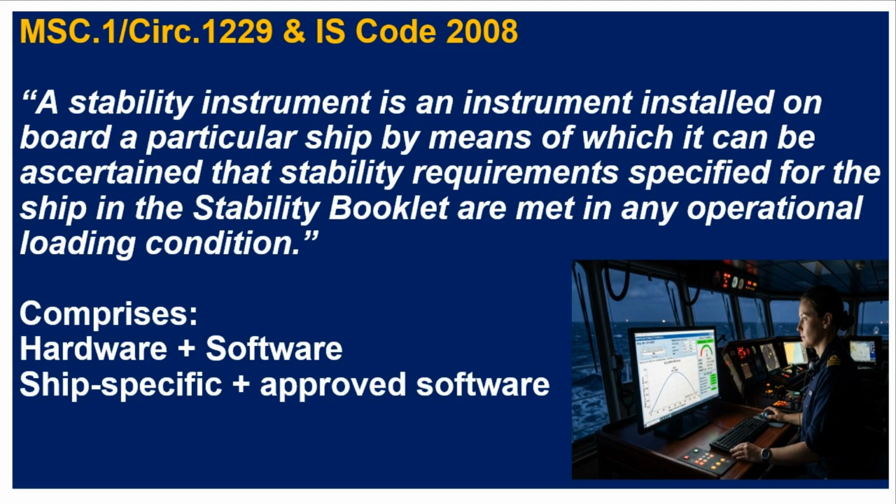A stability instrument is installed on board to ensure that all stability requirements mentioned in the approved stability booklet are satisfied in any operational loading condition. It consists of both hardware and software and is ship-specific.